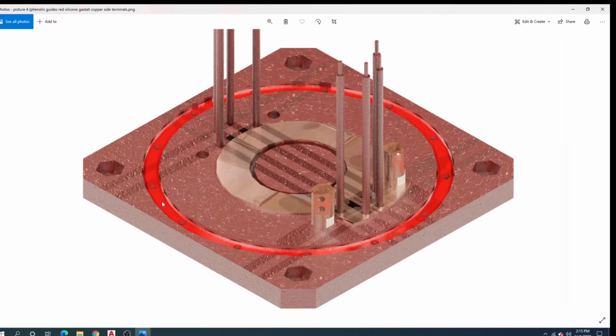Red silicone rubber is very durable, and it remains stable between -65 degrees up to several hundred degrees Fahrenheit. So it has good structural and material stability. It's good gasket material and has very good high temperature resistance characteristics.